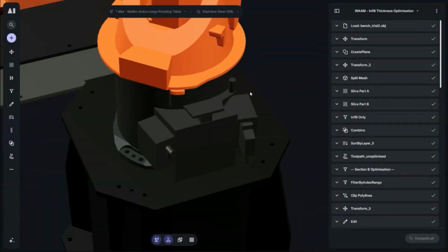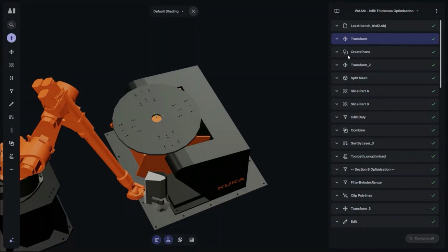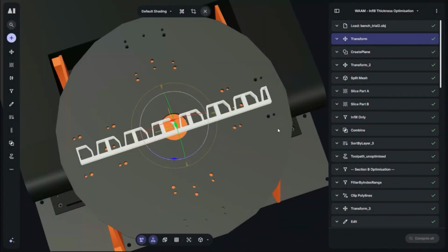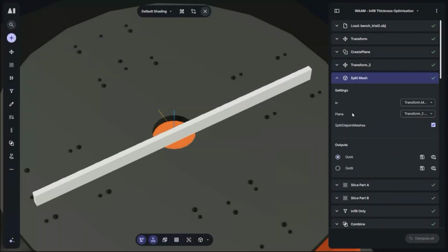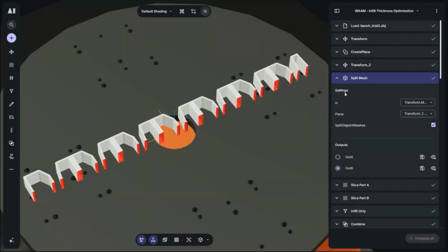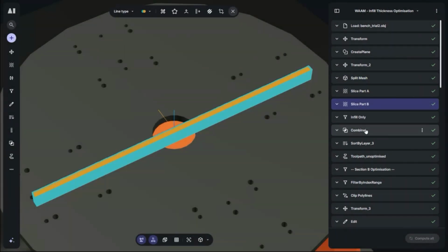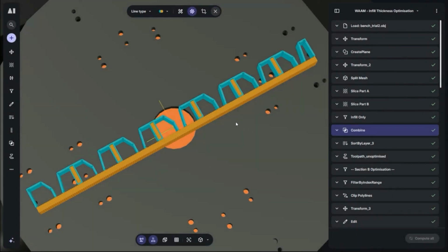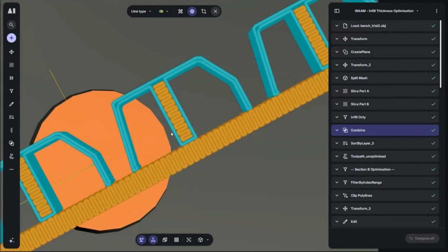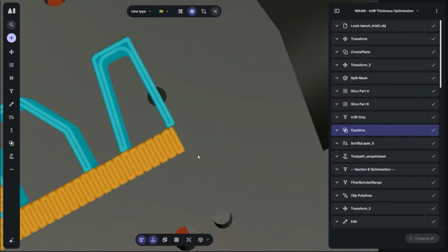I showed you that automotive part for infill optimization earlier. We can do something very similar for metals as well, using different kind of printing parameters. Like we said before, we have some limited CAD ability in the software. So here I've actually used a plane to cut this part into 2 halves, and make them different slicing settings. So if we combine those 2 halves, you can see that we have this kind of weaving and contour combination. But due to the nature of the multipliers of the weaves that we've used, we've got a gap here, and there's also a gap here.